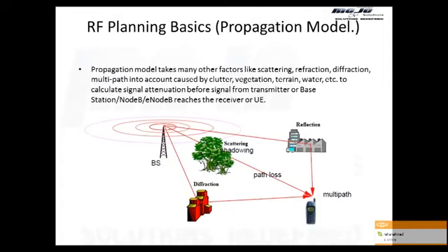So what is clutter basically? An urban environment has a different clutter because there are more man-made structures. Rural is different, suburban is different. So you should understand there are different clutters: rural, urban, suburban. Whenever you say propagation model, you will also see a thing called tuning, tuning your propagation model. Most propagation models need tuning, at least all the ones I know.